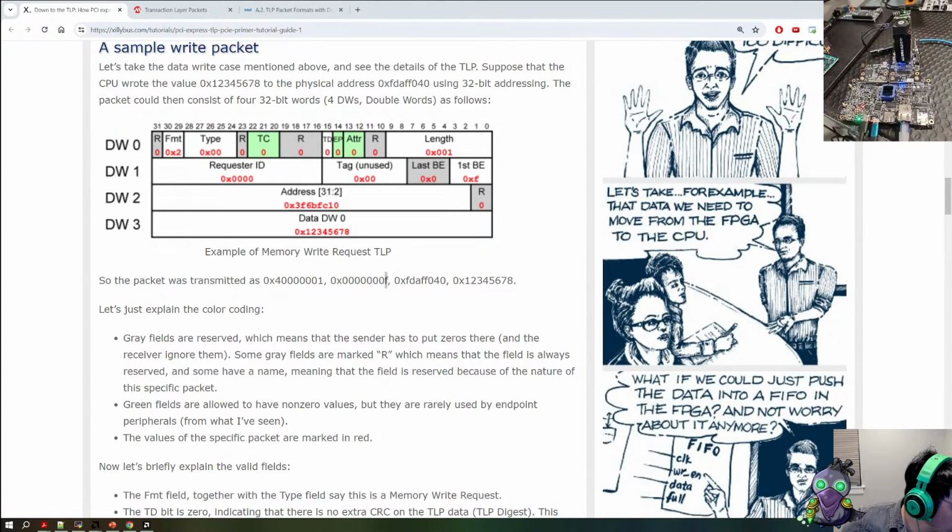So you're saying the root port BAR allows for address translation. A BAR is enabled, and any packet received from the PCIe link that hits a BAR is translated according to the PCIe AXI translation rules. Yeah, I'm going to have to look at the technical reference manual. I want to get some more details on that. Someone asked about AXI limiting the throughput of PCIe. We're doing AXI Stream and not AXI4. AXI Stream is just a data stream.